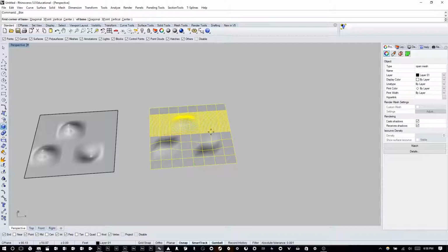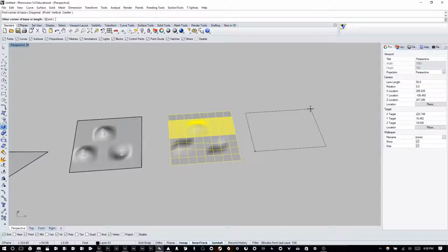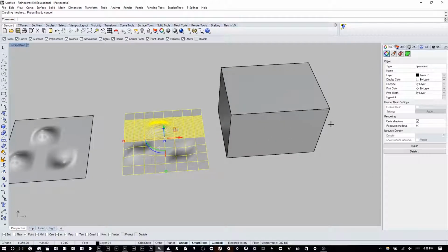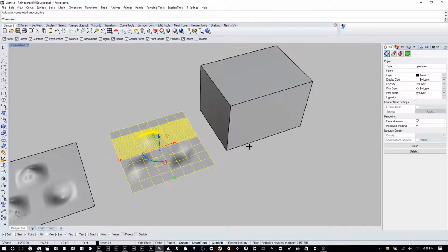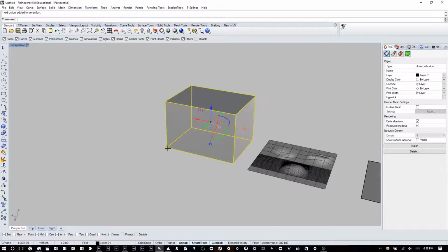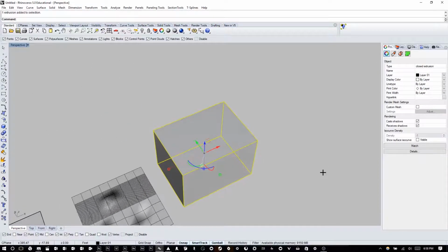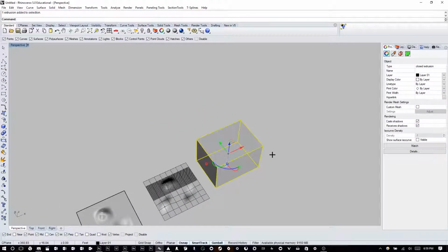And last but not least, I'll talk about a polysurface. So I'm going to create a box here. And all objects in Rhino that aren't meshes are polysurfaces. They're a conglomeration of different surfaces that have different faces in the X, Y, and Z direction. And so this box is a conglomeration of 6 different surfaces that I can then extract and do different things with.